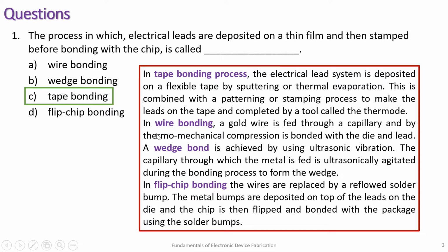So is that clear for all of you, the different types of bonding processes? Yeah. In wedge bonding, aluminum is also used. The thing is that it should have very high conductivity. In wire bonding also. And since we are working in nanometer dimensions, it should be strong enough and stable at the nanometer scale. That's all. We can go for gold, aluminum, etc. That is possible. Okay, I hope that's all.